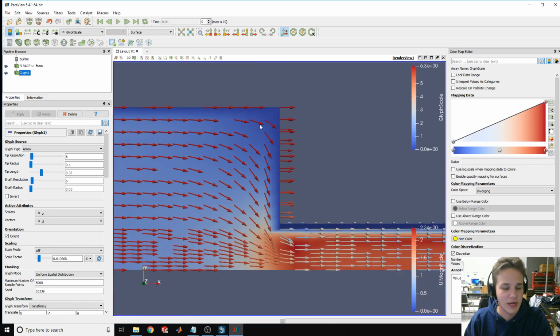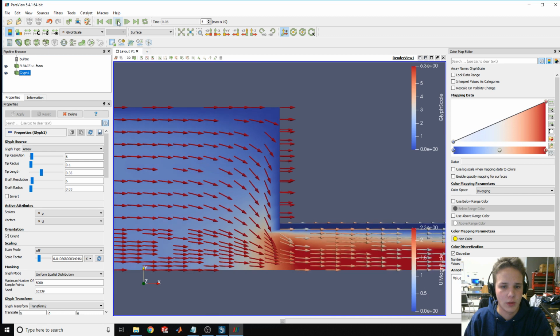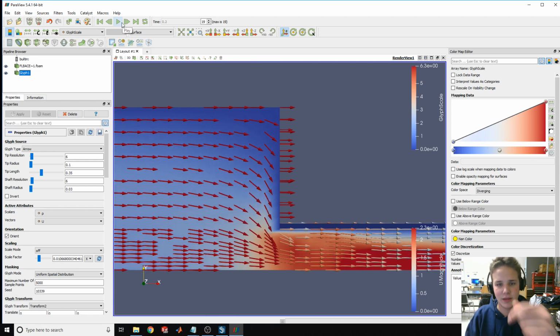So here there isn't that circulation. See, it stays right there. What this kind of shows us is that with low kinematic viscosity, it's going further in. It doesn't have that fluidity where it can ramble around and make a circulation area right here. No, it's going to go right in a radial direction and converge into this contraction area. And this is, I think, 4 inches to 1 inch, just for understanding.